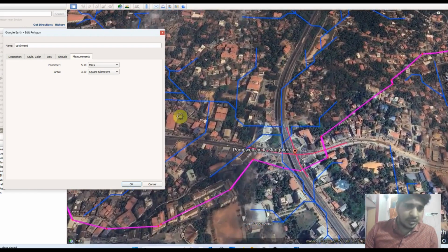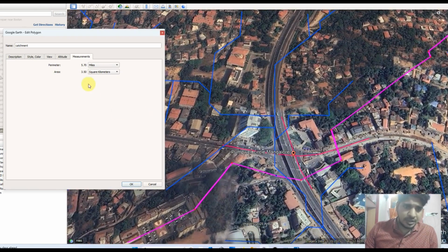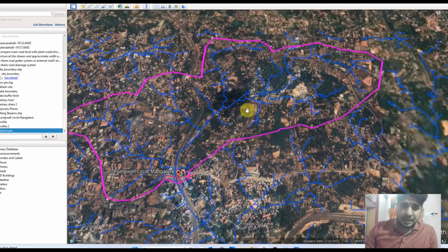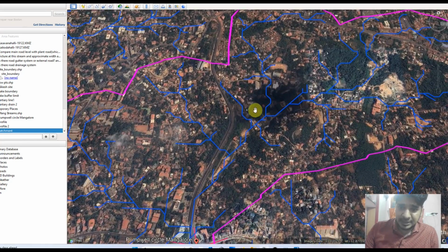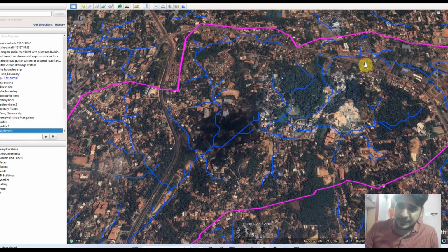So based on this, I can re-widen the roadway side drain, based on this 20 to 25 Qmax of the peak discharge. That is the option one I have. And option two would be proposing acquiring some lands. It's a kind of difficult task in India, but if any government lands are available, we can acquire them.